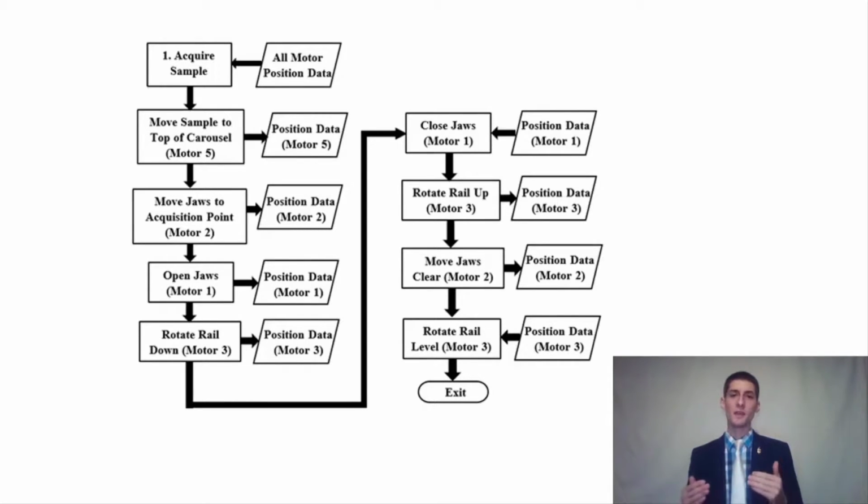By keeping track of where the jaws are and where they need to be, you can actually just reverse the operation. Go back the same number of steps that you went forward, and you'll end up in the same sort of place. This is very useful in keeping high fidelity tracking of the position and not having to have so many sensors involved in locating the actual component.